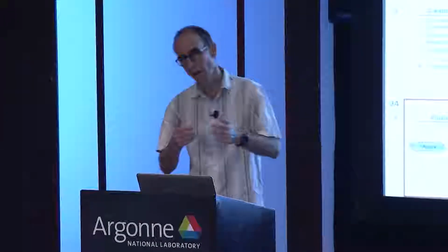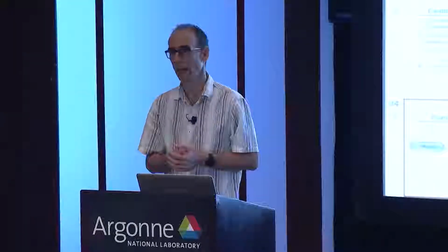So why is there this Apply button? ParaView is designed to work with large data, and if auto apply were on, you would make a change and then ParaView would hang and process that large data. If you have this separate step where you say Apply, you know that a large processing is going to come, and you are prepared for that.